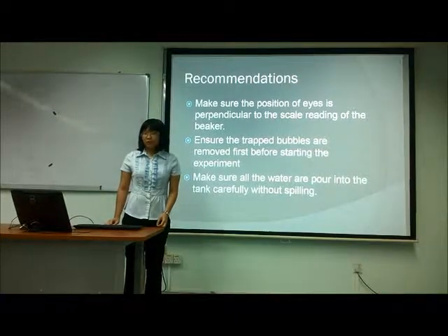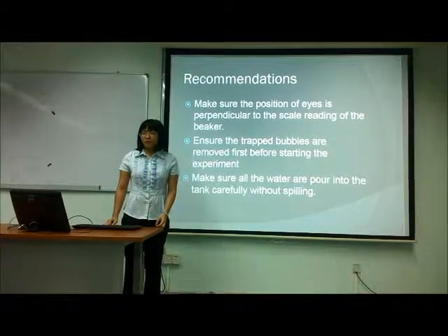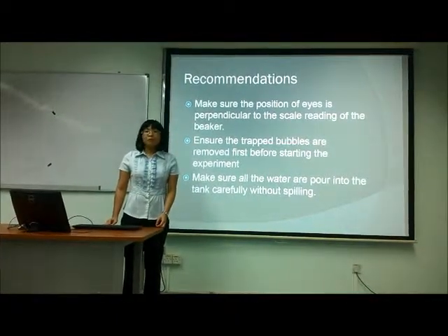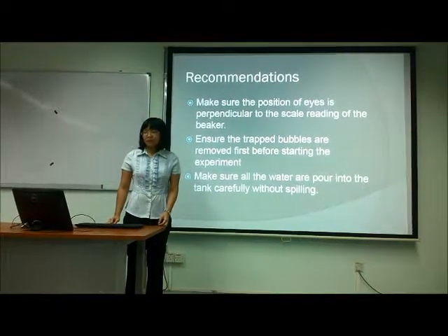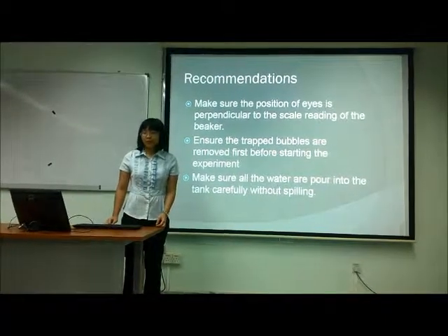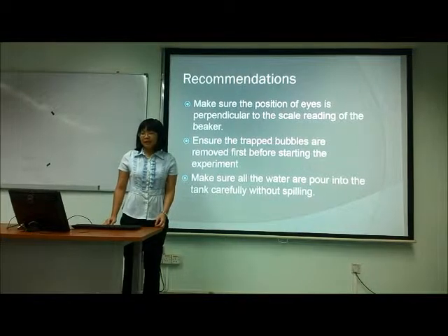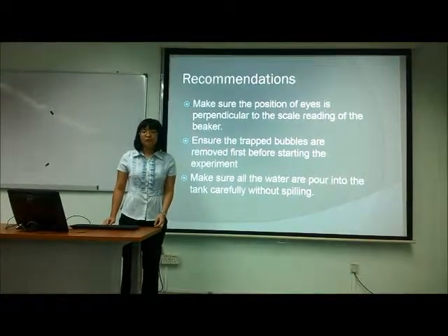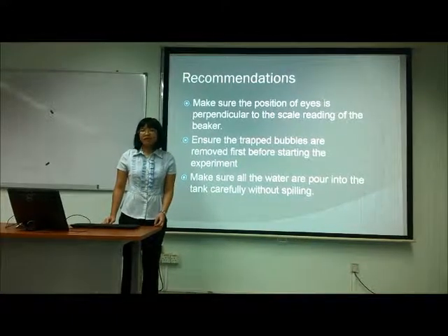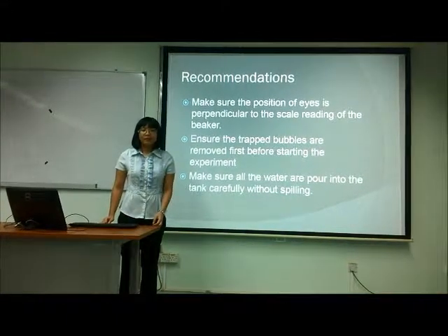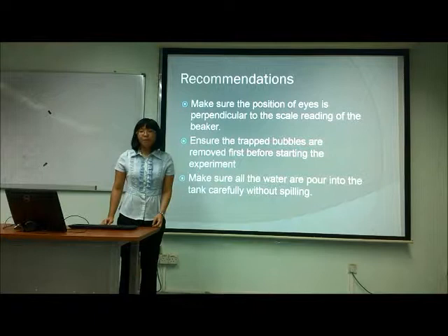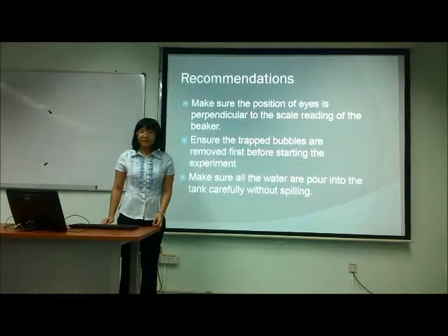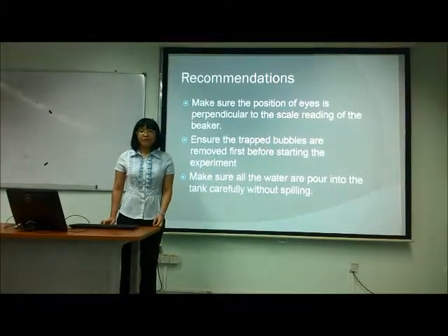The recommendations suggested are as below. First, we should make sure that the position of our eyes is perpendicular to the scale of the beaker when taking the reading. Next, we should ensure that the trapped bubbles are removed before we start our experiment. And finally, we should make sure that there is no water spillage when we are pouring the water into the tank. And now, I've already finished my part.